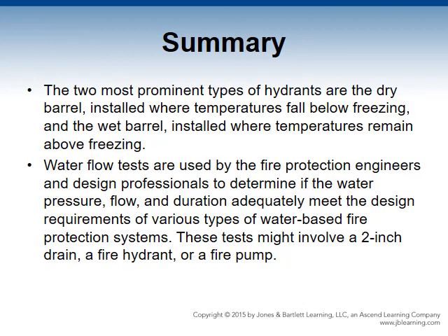The two most prominent types of hydrants are the dry barrel, installed where the temperature falls below freezing, and the wet barrel, installed where the temperature remains above freezing. Water flow tests are used by fire protection engineers and design professionals to determine if the water pressure, flow, and duration adequately meet the design requirements of various types of water-based fire protection systems. These tests might involve a 2-inch drain, a fire hydrant, or a fire pump.